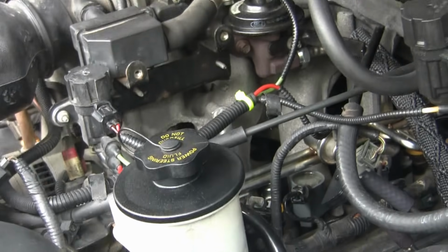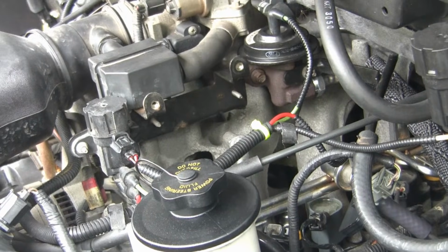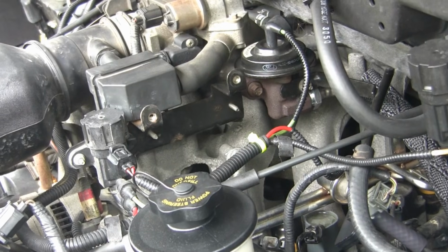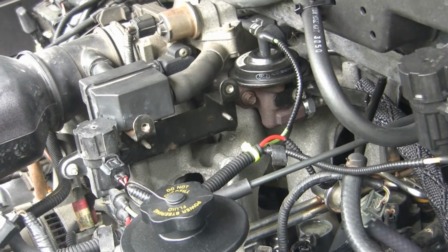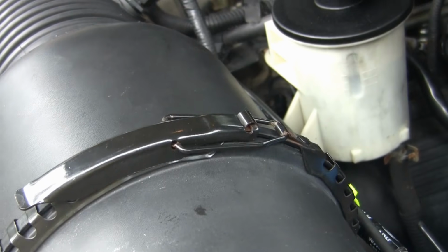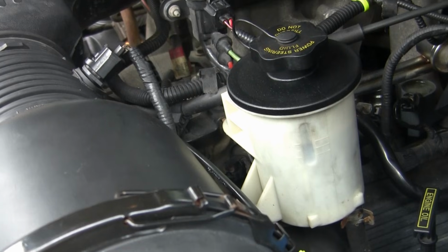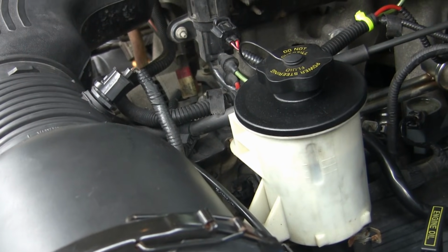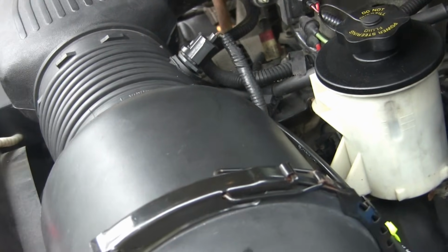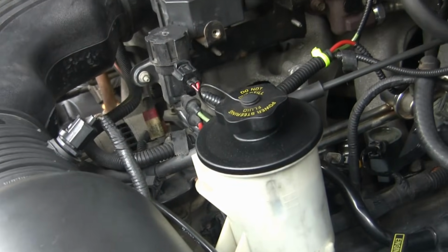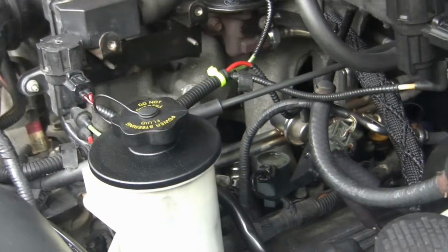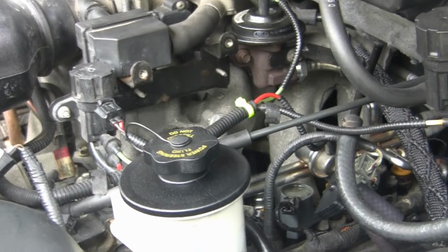This particular vehicle was idling really fast, about 1200, 1300 RPMs, and it's running a little bit rough too when you're sitting at idle like at a red light. But as soon as I cleaned that mass airflow sensor with that spray, idle went down to about 650, 700, and it idles very smoothly now. So $8 and probably half an hour's worth of your time. Be something to take a look at, especially with high mileage vehicles. Don't mess it up though. I understand it's an expensive part.